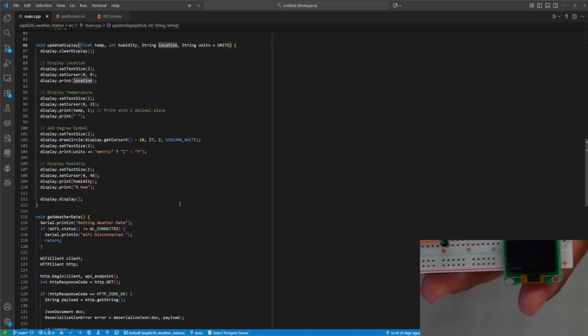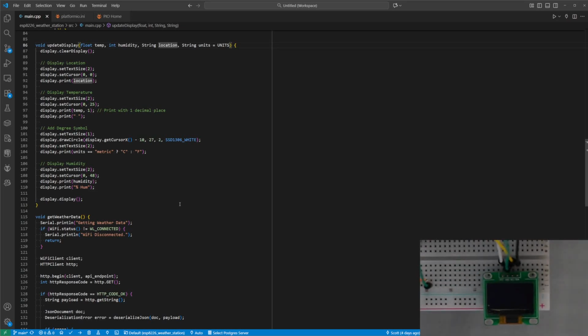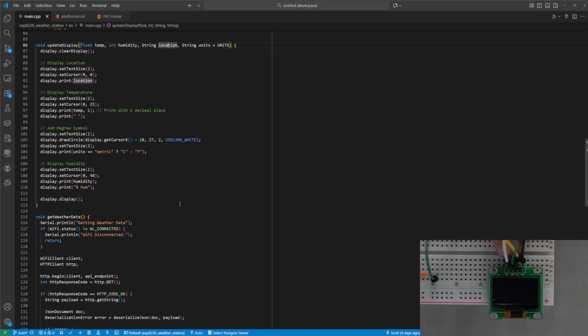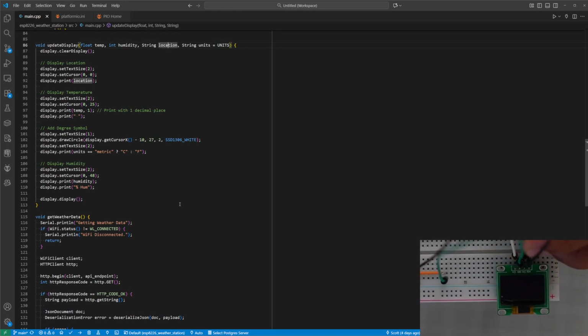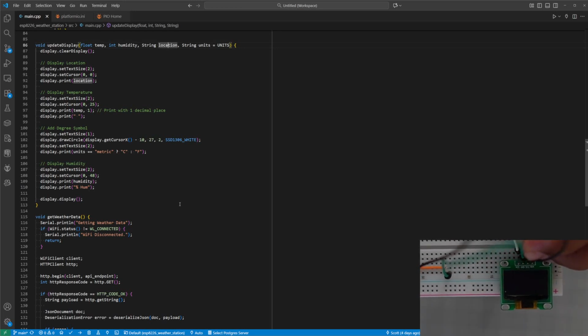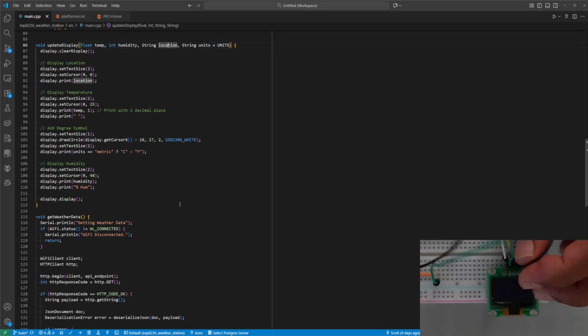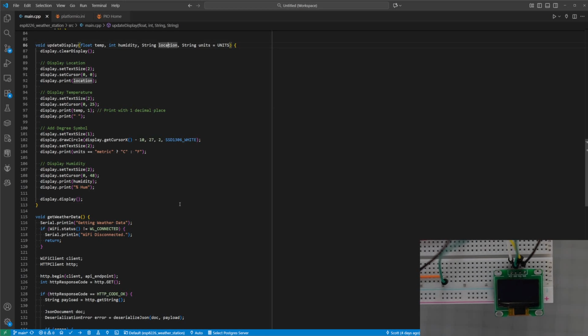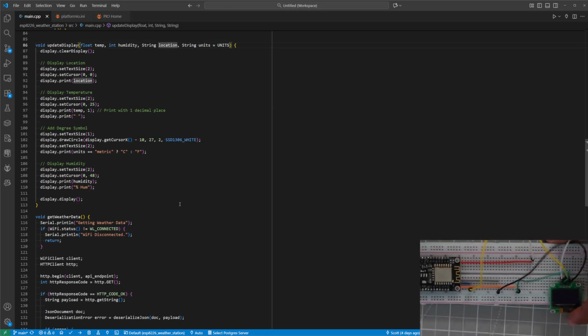And then if we look at the OLED screen, this white one is just jumpered from the 3.3 volts, and that's running into the VCC pin of the OLED screen. Ground is running to ground, which is just the green here. Yellow is the clock line. This is running to D1 for the clock. And then black here is running to D2, which is the data. And it's a pretty simple wire up, no resistors or capacitors needed, just straight plug and play.